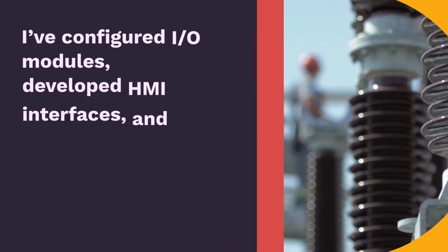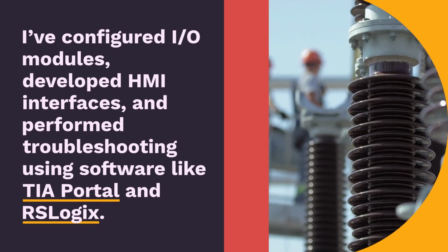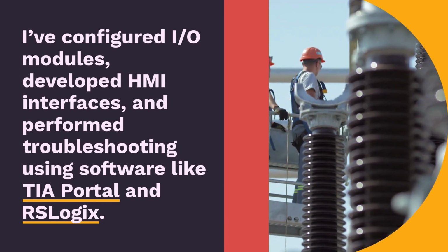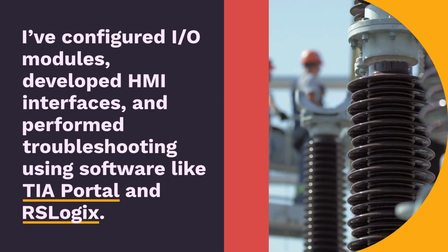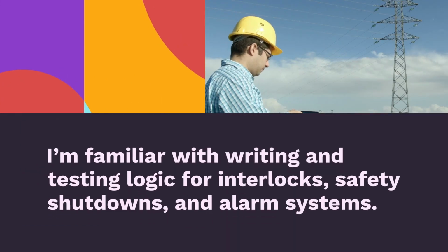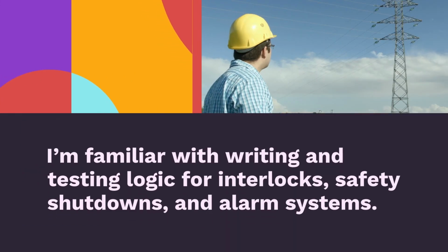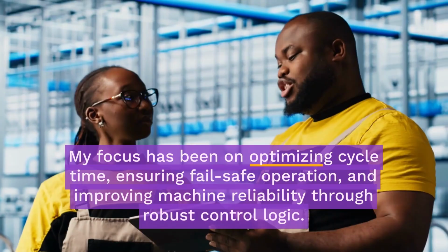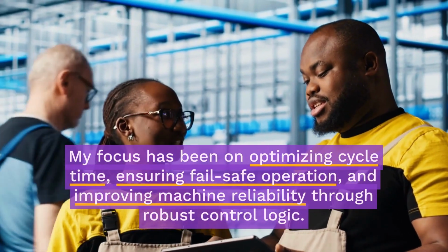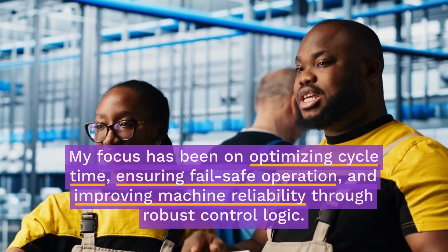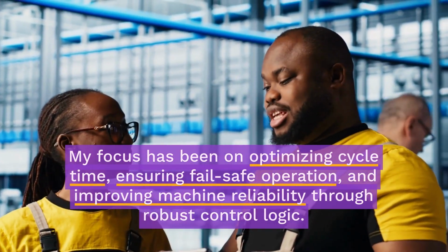process automation. I've configured I/O modules, developed HMI interfaces, and performed troubleshooting using software like TIA Portal and RSLogix. I'm familiar with writing and testing logic for interlocks, safety shutdowns, and alarm systems. My focus has been on optimizing cycle time, ensuring fail-safe operation, and improving machine reliability through robust control logic.